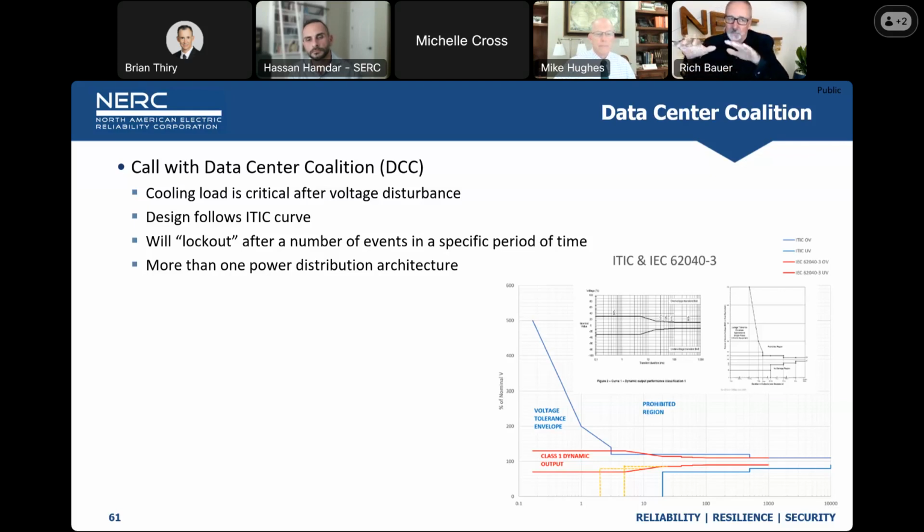And that's a great way, as the previous person said, if we have a large loss of load, that's the equivalent of a large injection of extra resources on the system, right? So the 2 things that happen, physically on the system, is that the frequency will go very high and the voltage will go very high.